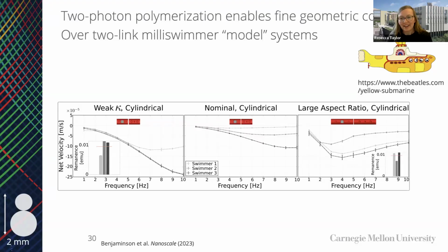We're also doing work in computation, but this in and of itself is complex because you've got elastic components and you've got fluid structure interactions, right? And so this is one of these new challenges for soft squishy robot simulation. Most of our computational fluid dynamics modeling is not set up to do this well.